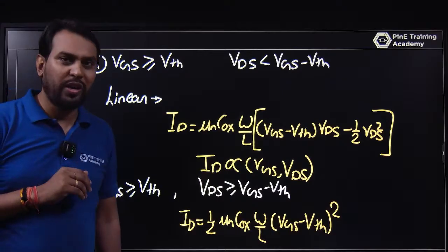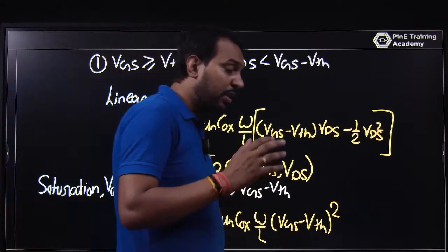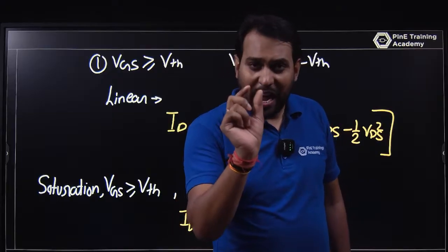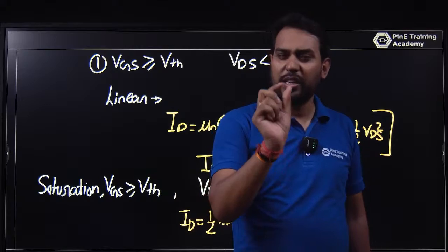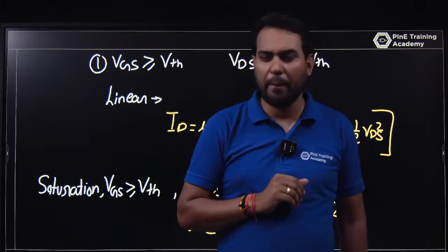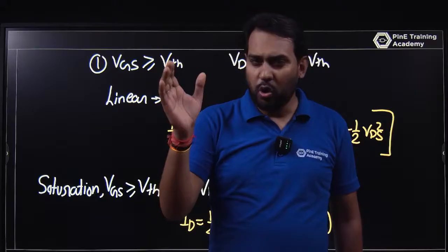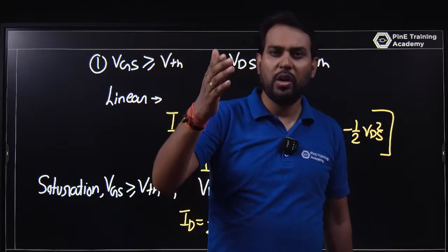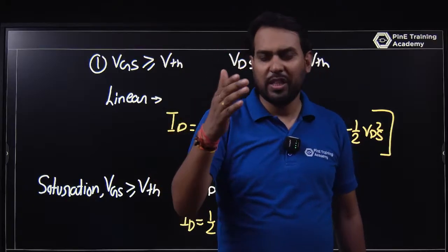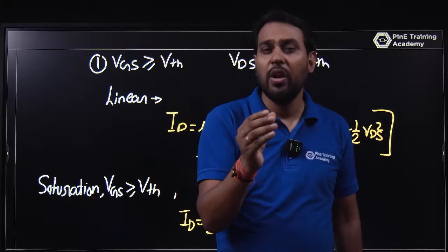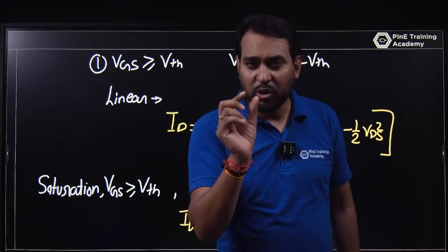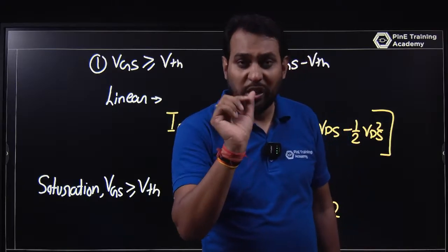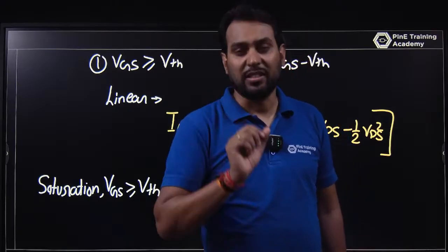For the MOSFET, sub-threshold conduction means VGS is near about VTH. We are trying to keep ID very, very small, nearly 0, that is nanoampere or picoampere. But once you go to a lower technology, from 180 nanometer to 90 nanometer to 65, 55, and then 45 nanometer, you find the sub-threshold conduction effect increases. It means near VGS to VTH, the current is large.